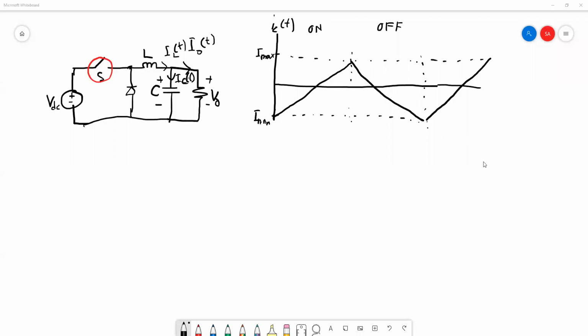So, this is the lesson on the ripple output voltage. Actually, the ripple output voltage, or sometimes we usually refer to it as delta V out, is a very important parameter in designing the DC-DC converter. You may be confused about what ripple actually is, because the output voltage here should be a DC voltage, right? A constant DC. But because it involves switching, if you zoom in on this area, it actually has some ripple.